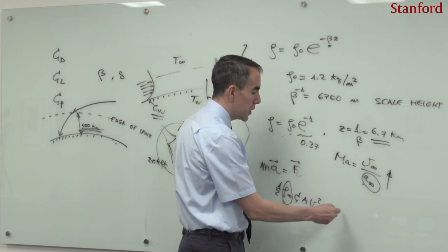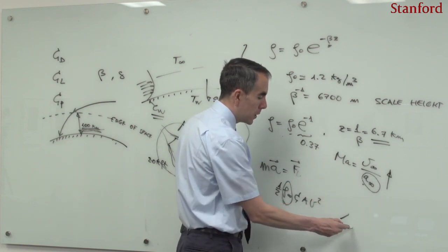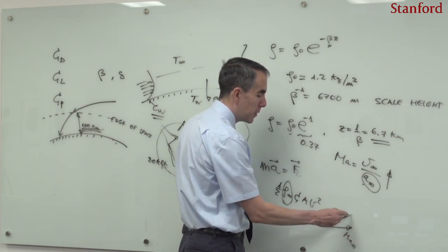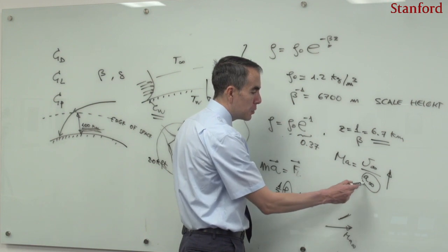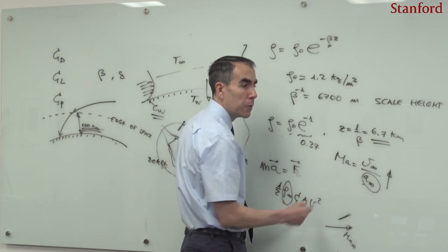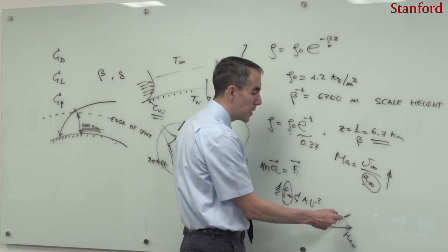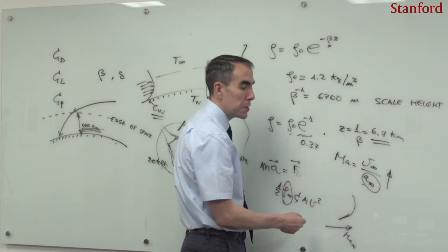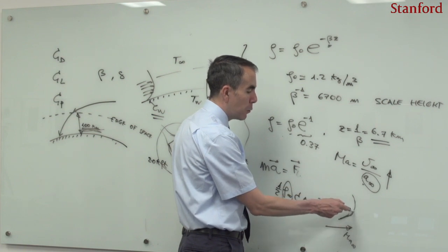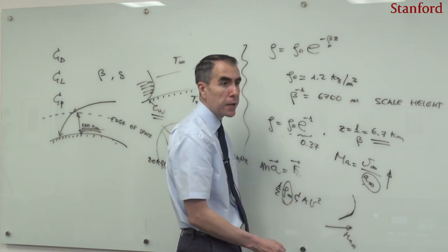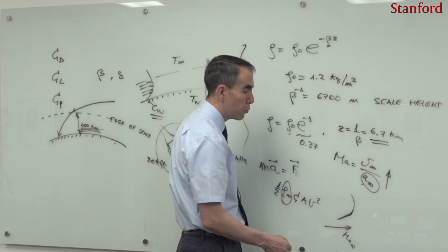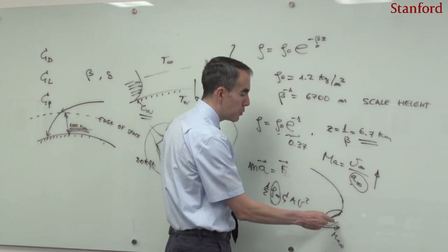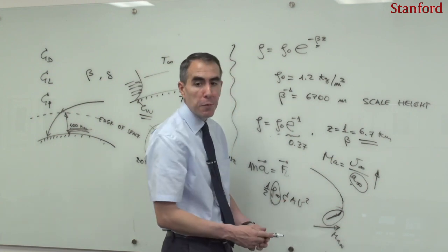As the altitude decreases, the temperature in the thermosphere decreases, and the Mach number increases, relatively speaking, right? So that's why you see first in that plot of the Mach number an increment, and that's due to the decrease in the speed of sound through the atmosphere. The temperature there is still large, and then a nominal Mach number across the mesopause, the one we have always been talking about. Let's say in the case of the Apollo, it was closer to 36. So remember that this part here is always because of the effect of the thermosphere.